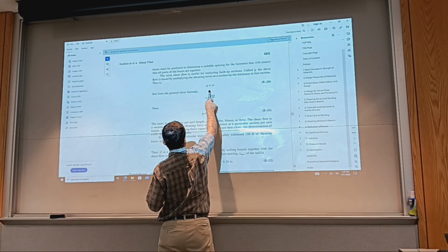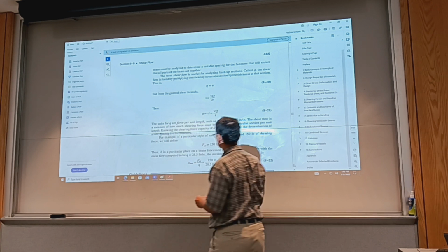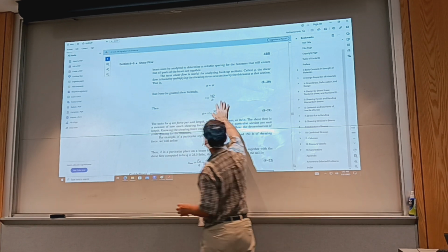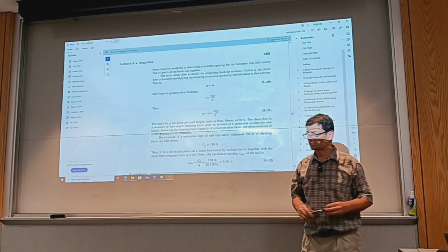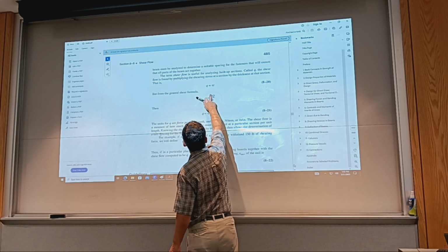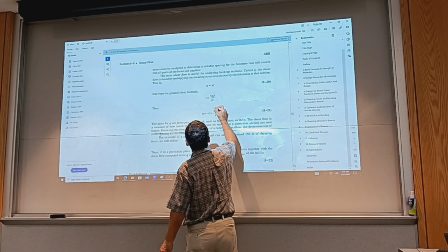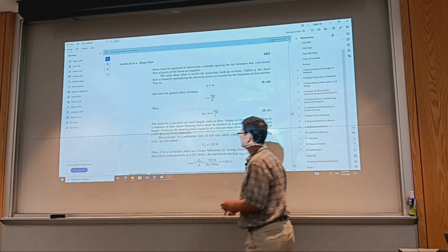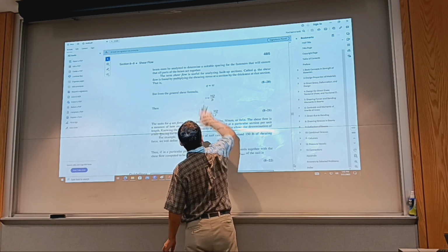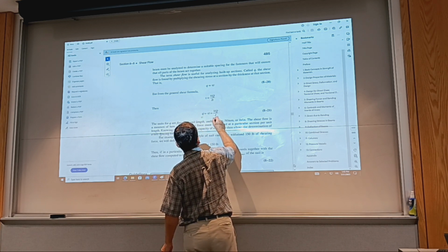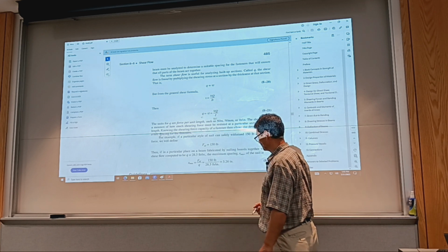It's found by multiplying the shear stress at the section with the thickness of that section. We know how to evaluate the shear stress caused by bending with this equation: shear force from the shear diagram, first moment of area, moment of inertia, and thickness. And then we can relate q to what is left of the earlier equation.